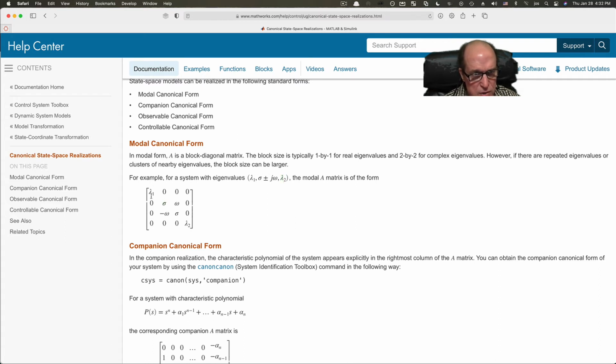And then here you can see there's a real eigenvalue here, a real one there, and this little 2 by 2 block is the biquad. And it came out looking like this. But this can be any little 2 by 2 state space matrix. What we saw was minus A1, minus A2, and 0 and 1 on the bottom. So it's whatever you want there. There are a lot of different forms there. It depends whether you started with direct form 1, direct form 2, normalized, lattice. There are all these different forms. You can get a lot of different things here.